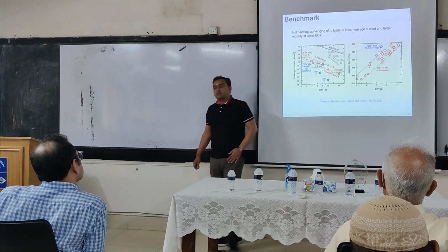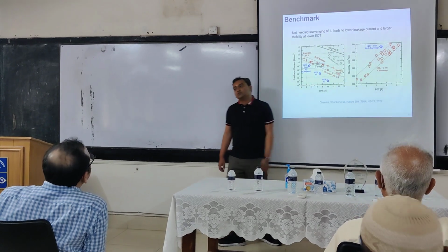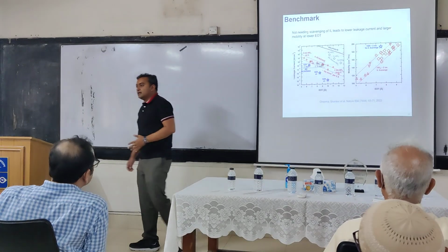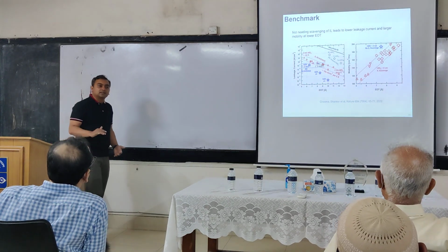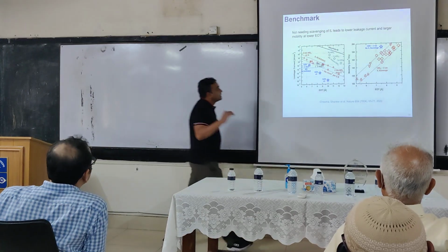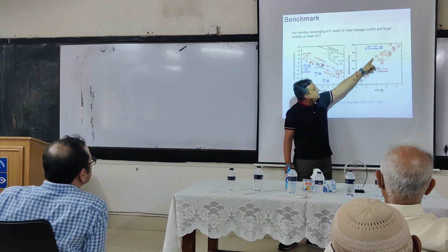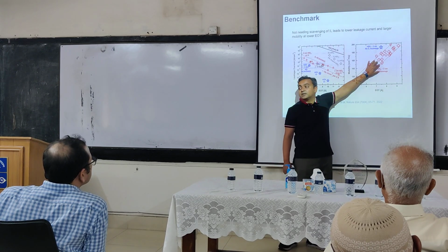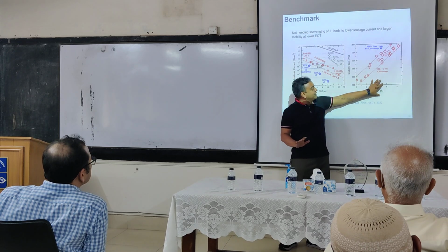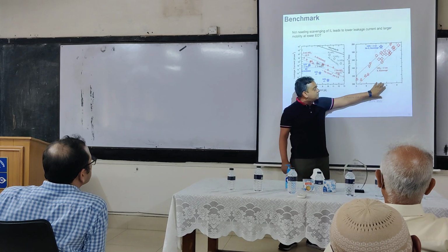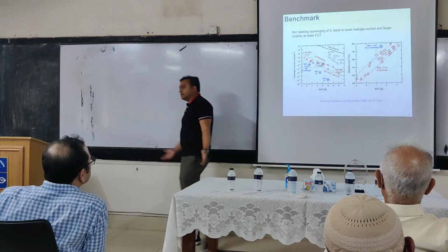Okay? And again, this is not just one versus the other. This is an industrial benchmark. So we can actually do better than what industry has. Now, when you try to take SiO2 out of silicon, silicon does not like it. As a result, the mobility in the silicon goes down. So similarly, if you look at it, as you are reducing your thickness, meaning capacitance is going up, mobility tanks. This is the industrial benchmark. We don't do any SiO2 removal, which is called scavenging. We don't do that. As a result, our mobility is not affected. So our mobility remains there.